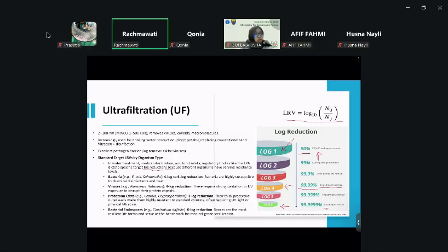Of course, if you want healthy water, you don't want to consume pathogens in water, so you might want to aim for a higher log. But the institutions have a standard which is still deemed quite safe for human drinking water. For bacteria like E. coli or Salmonella, the standard is log 4 to log 6.